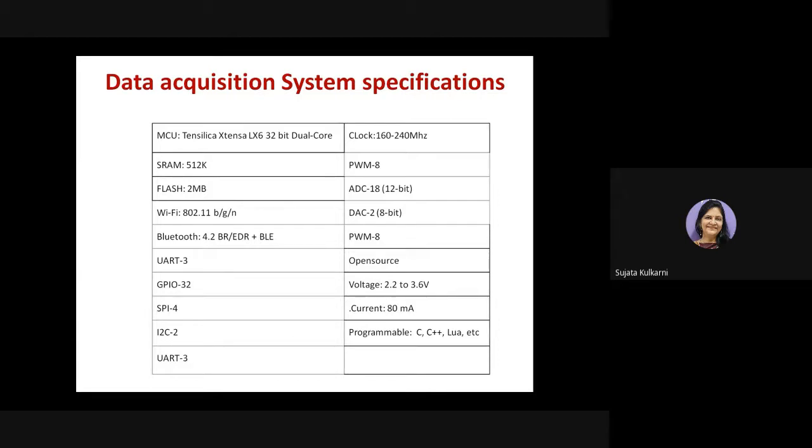So our data acquisition is multi-channel analog as well as digital, and also has digital to analog converters, up to 2 channels. That means it's like an arbitrary function generator. Whatever waveform you design through software should be available at the output. So that's the arbitrary part.